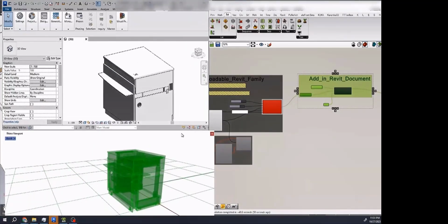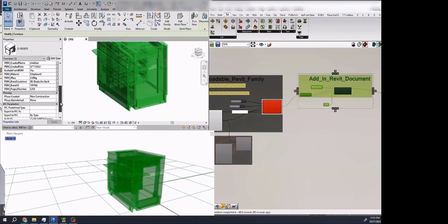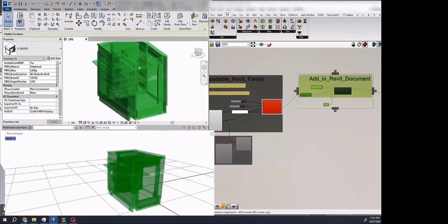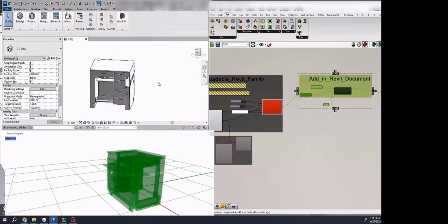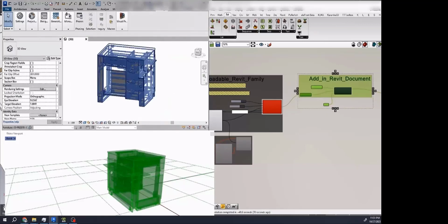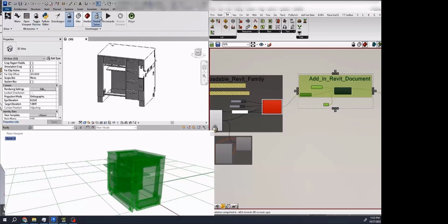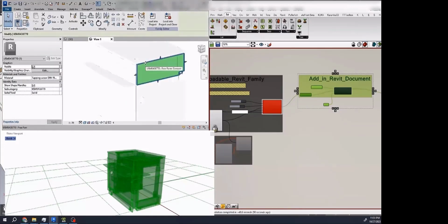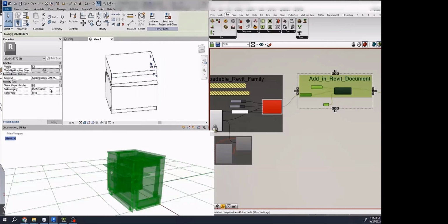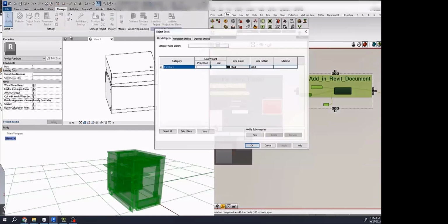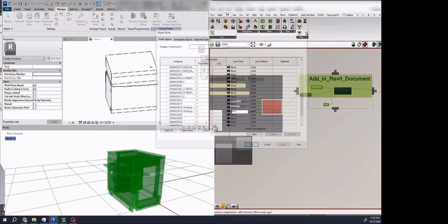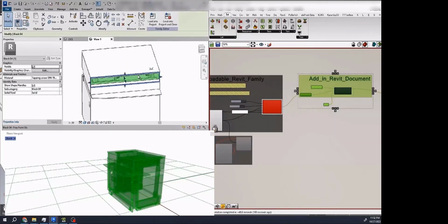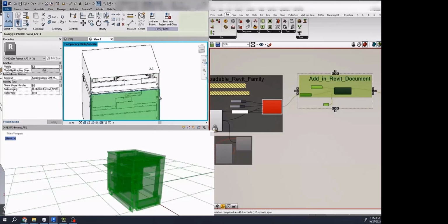And now you can see here we have a native Revit family with all the metadata embedded in there as native parameter sets. You can also go into the family editor, and when you look at it there, all the parts come in, which can be edited by each designer or planner. And yes, subcategories, everything comes into Revit automatically.